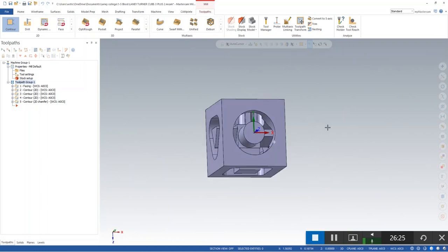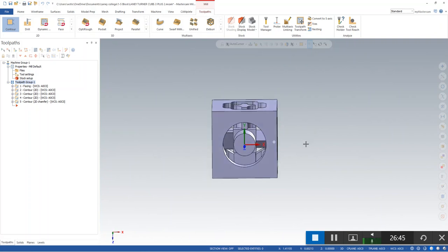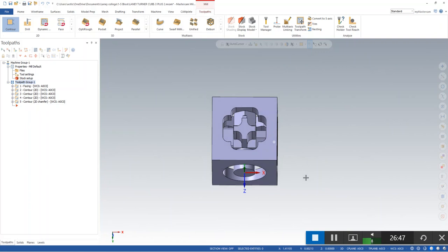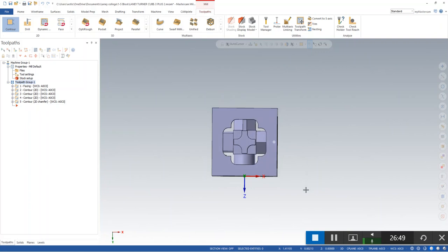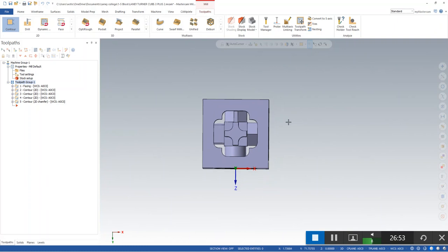So with the TRT, the spindle is looking down on the part, right, this is our view. So when the TRT rotates 90 degrees, it's going to rotate the part, and it's going to show us this face right here. That's going to be our A90 and C0.